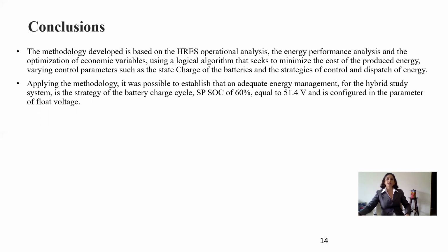Applying the methodology, it was possible to establish that an adequate energy management for the studied hybrid system is the strategy of the battery charge cycle with a set point of the state of charge of 60%, equal to 51.4 volts configured in the float voltage of the inverter.